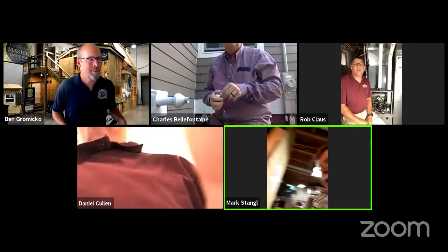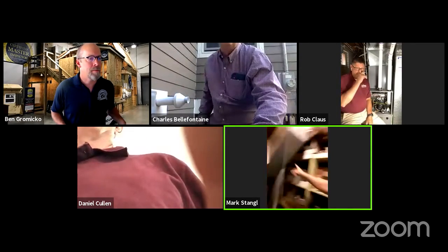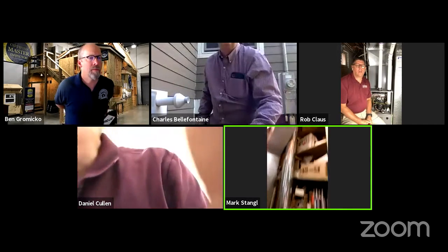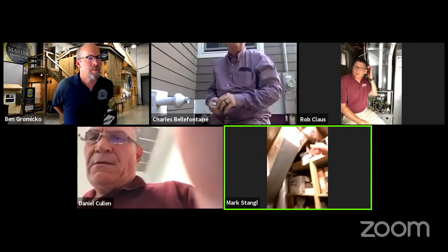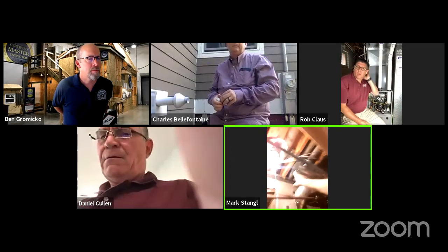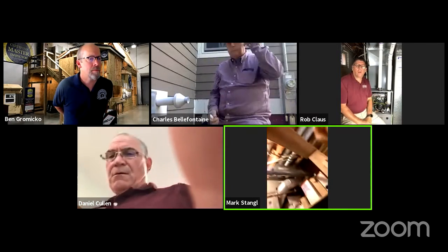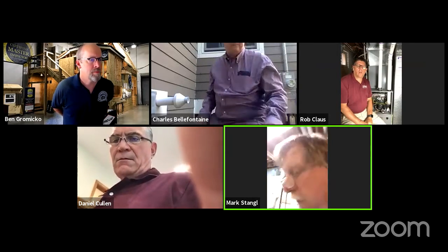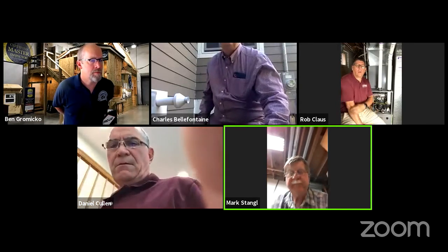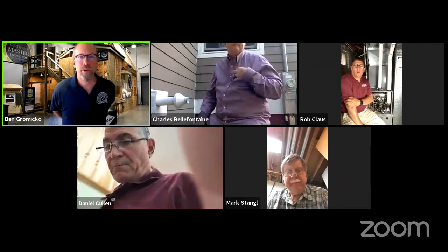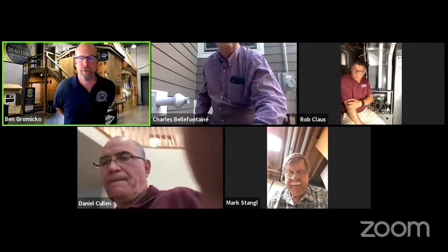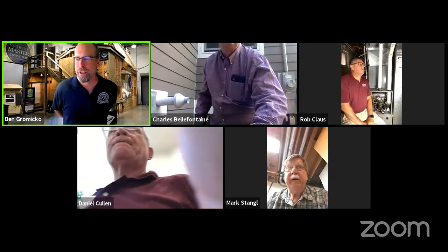One other thing I want to mention is that this home has a large vent here that you can see, 6-inch vent, goes directly outside, and there's another one up above right here, and that brings combustion air into this mechanical room, which contains both the furnace and the hot water heater. And you need that because it's not category 4. You're not drawing air directly from the outside. You need that combustion air.